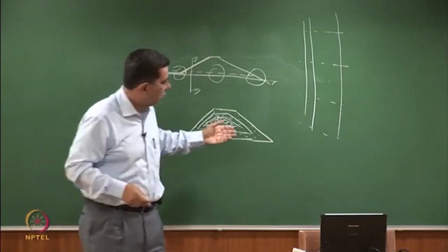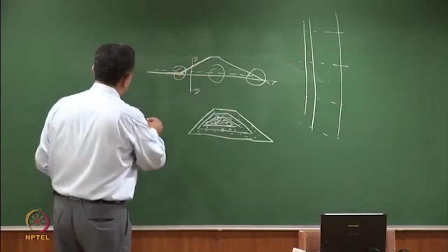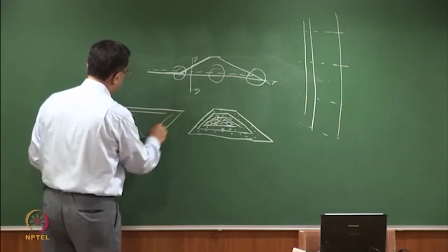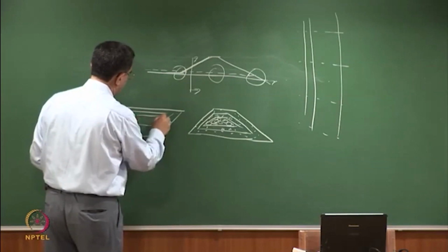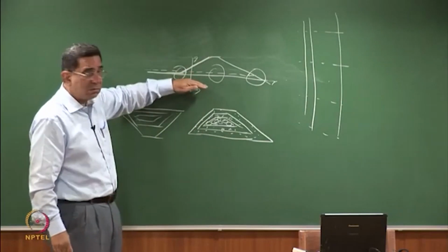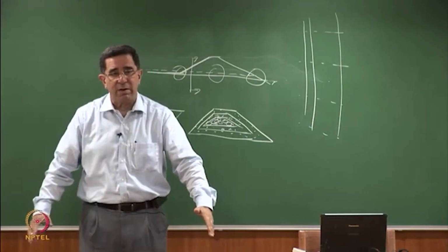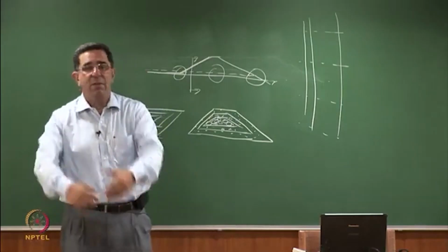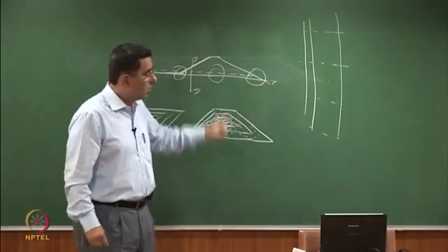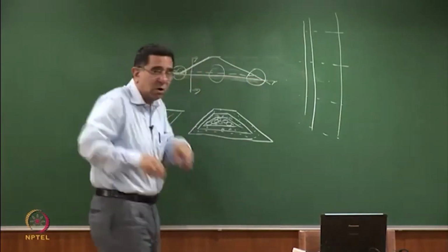And this is, if you want to make the drain below the ground, then you can make a trench drain. How does a trench drain look like? Exactly the opposite of what it looks like here. So this is below the ground, and this is above the ground. So if this is your ground, either you can have a trapezoidal drain, or you can make a trench and have a drain, either of the two. But you would be collecting the fluid there, and this would then be lined, because you would have to line this so that whatever the water is going out, you are not supposed to let it go into the ground.